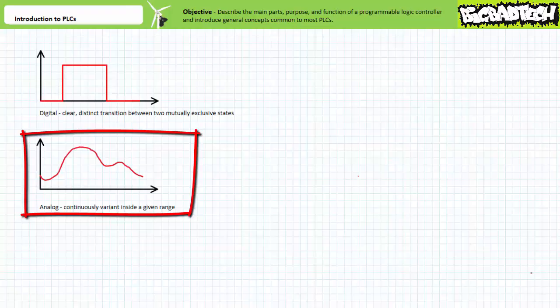A variable solenoid for a hydraulic proportional valve would be an example of an analog output, in that movement of the spool varies in proportion to the electrical output. More voltage output means more movement of the spool and consequently more flow. The analog nature of the output signal would allow an appropriately proportionate response for a given input condition.